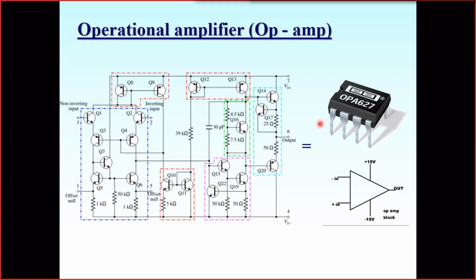But to be able to use the operational amplifier in this mode, where the output may be both negative and positive, we have to feed this amplifier with a so-called bipolar power supply. So we have to have a power supply which has a minus pole, a plus pole, and some zero point between the two poles. In this case, the output will be a voltage which may be both positive and negative with respect to this average zero or ground pole.